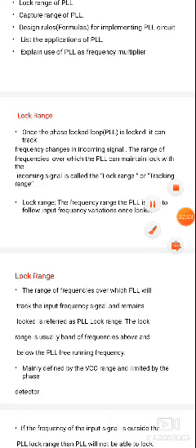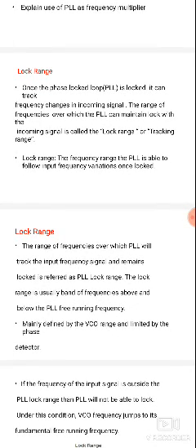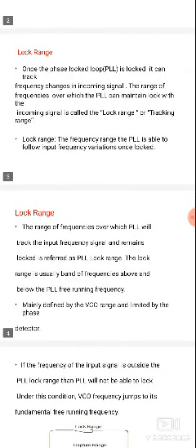We have also completed the 566 IC. The 566 IC is mainly used as a voltage controlled oscillator. The voltage controlled oscillator matches the output frequency with the input. So it is a closed loop feedback system. Whenever the output frequency is matched with the input voltage, the circuit will be working in locked mode.